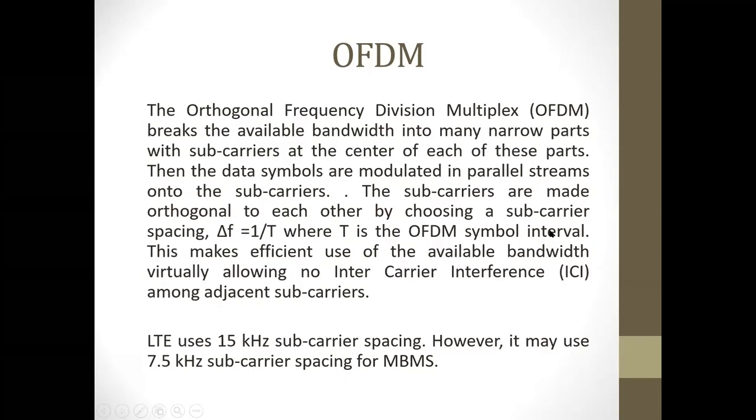Well, it was known before. People always had the understanding that if I split my data and transmit together onto multiple carriers, then I can enjoy small bandwidth, which leads to flat fading. This frequency selective fading has always been a really nagging issue for RF engineers. So I can enjoy flat fading, but people couldn't do that.